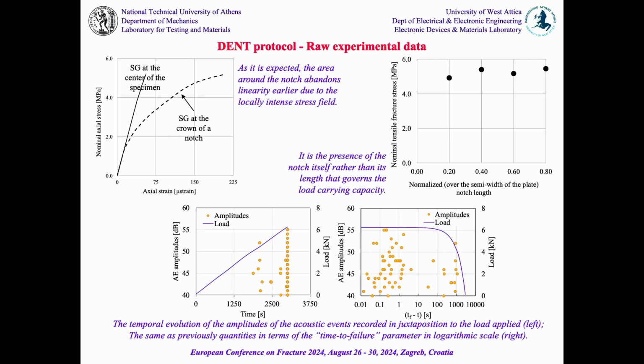Obviously, as we are very close to the crown of notches, we have non-linear response for very early loading steps, while the main specimen is almost linearly elastic. It means that we have a kind of inhomogeneity induced during loading. And again, the majority of acoustic events are generated during the very, very last seconds of the procedure, which makes the analysis of the results very difficult.